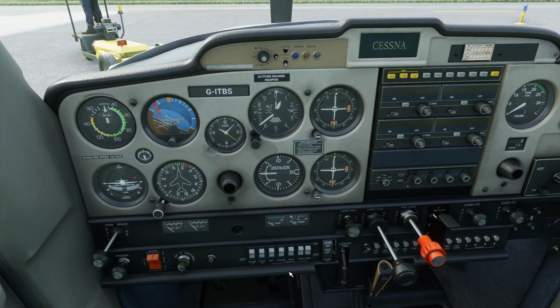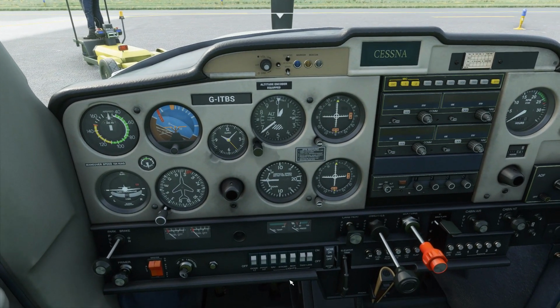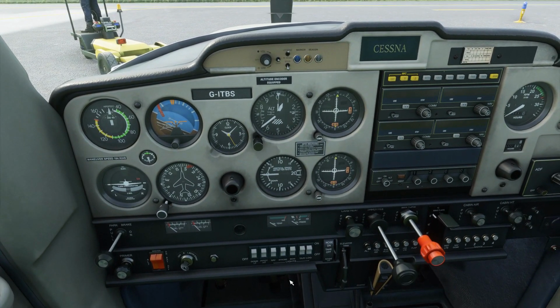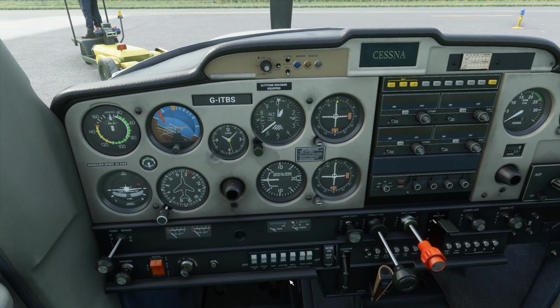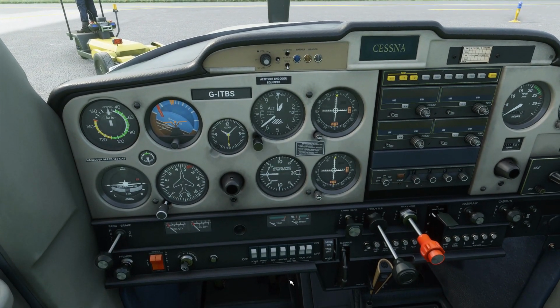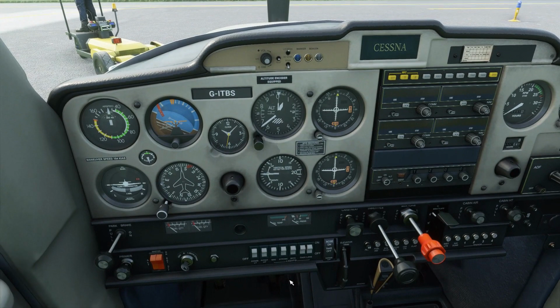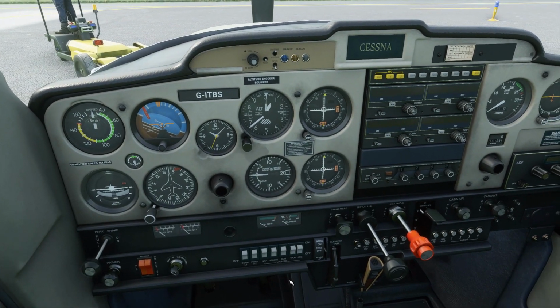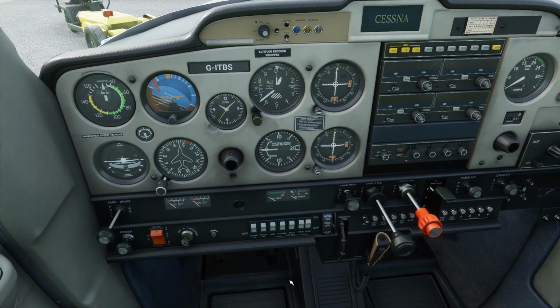We turn that on just before starting the engine. That allows the ground crew and any other people nearby to see a clear indication that we are about to start the engine, and also makes it more visible during all phases of the flight that the engine is running.